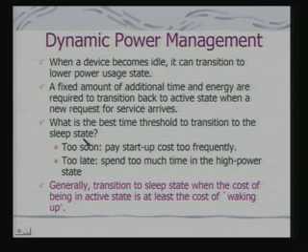So, dynamic power management, because these power modes have to be controlled by the software or the user. What does dynamic power management therefore imply? When a device becomes idle, it can transition to a lower power usage state. A fixed amount of additional time and energy is required to transition back to the active state when a new request for service arrives. What is the best time threshold to transition to the sleep state? Because this is the key question.